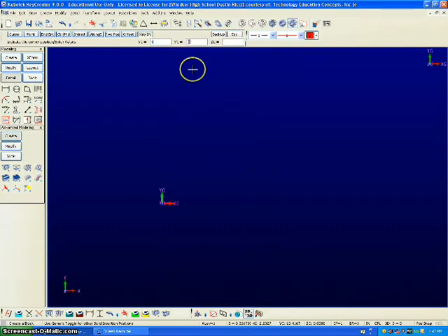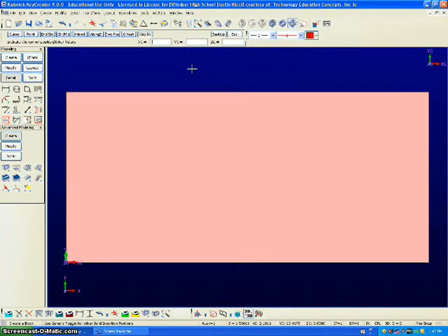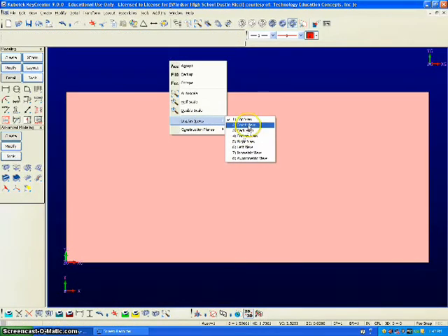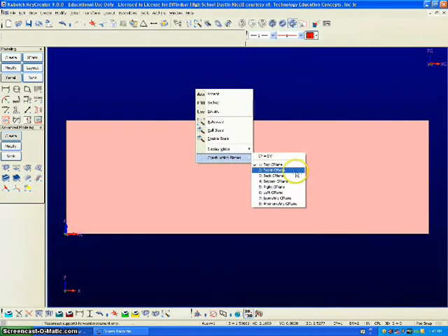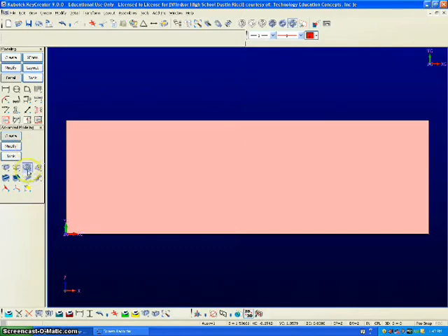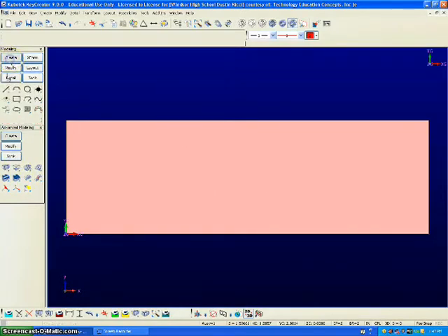and key it in the middle, 0, 0, 0. Control A to center your block. We're going to start out by trimming the front view. I'm going to take a smaller block out of our main block. So make sure you're in your front view and display and construction, and go to create line parallel distance.